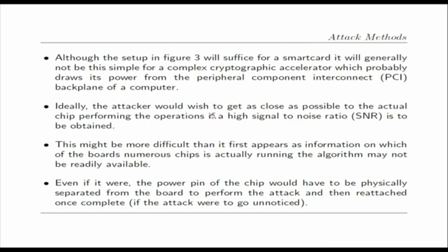Ideally, the attacker would wish to get as close as possible to the actual chip performing the operation if a high signal to noise ratio is to be obtained. This might be more difficult than it first appears, as information on which of the numerous chips on the board is actually running the algorithm may not be readily available.